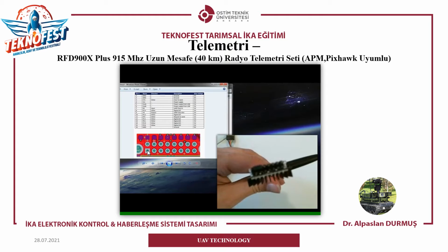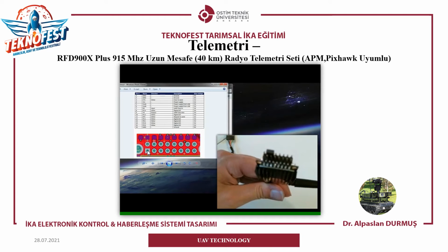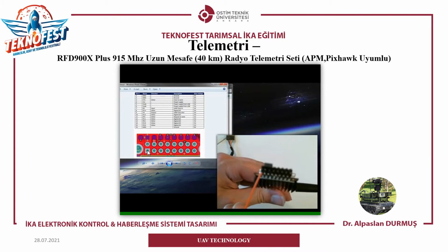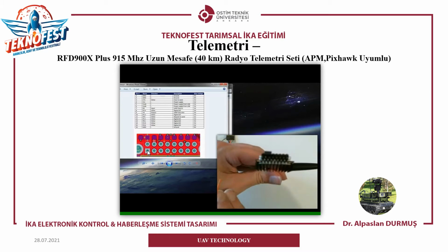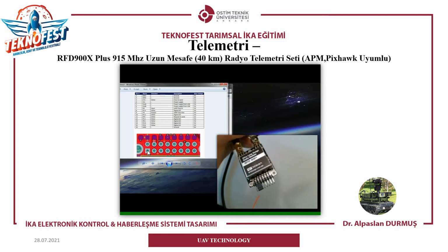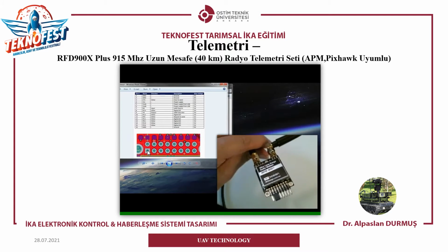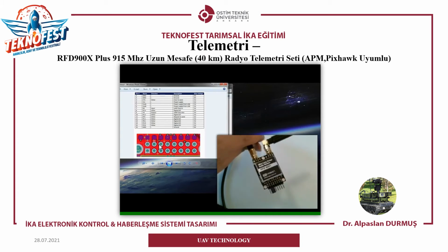Camera will focus. There's 2 rows here. This bottom left one is ground. On the top there's a little jumper. This jumper is going between pins 4 and 6, which is needed to bring power from the FTDI cable to the radio.